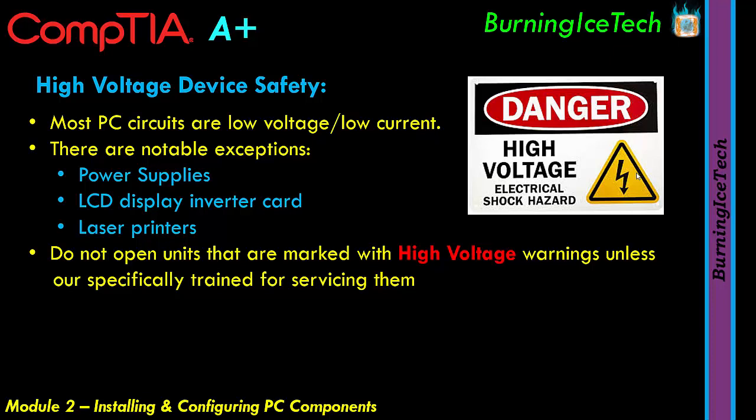So if you find yourself needing to open a laser printer, if at all possible, I highly encourage you to turn it off and also to unplug it, never mind turning it off. Something which is also worth noting, which is not power related, is that these laser printers get very, very hot. It's not related to the topic, but it's a general rule of thumb I want you guys to be aware of. Do not open a laser printer while it's hot. Unless you know what you're doing, you're going to get burned. So never mind getting electrocuted, you're also going to get burned. So watch out for that.